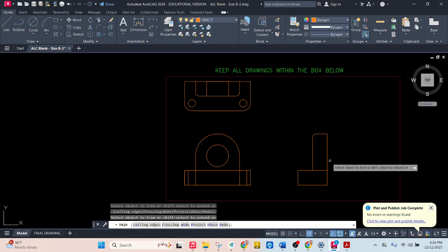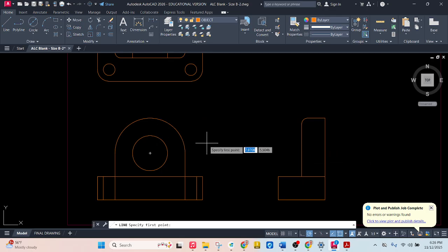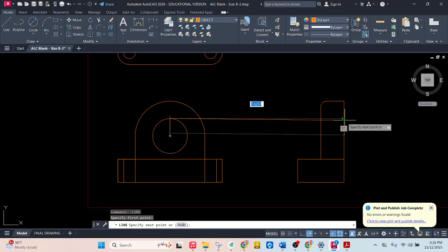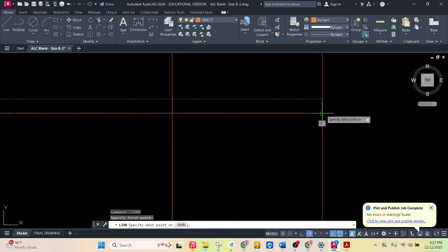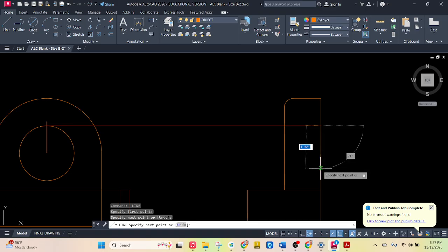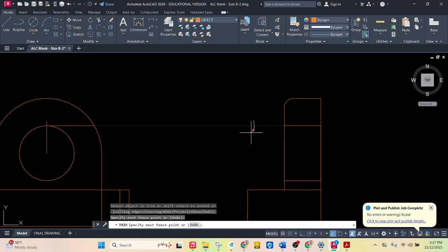And over here, we're going to get this circle, that hole that goes over there as well. Goes up. Straight over. Goes down 1.5 inches. Tab 90, enter. Goes back over here. I'm going to trim the extra stuff. That, that, that.